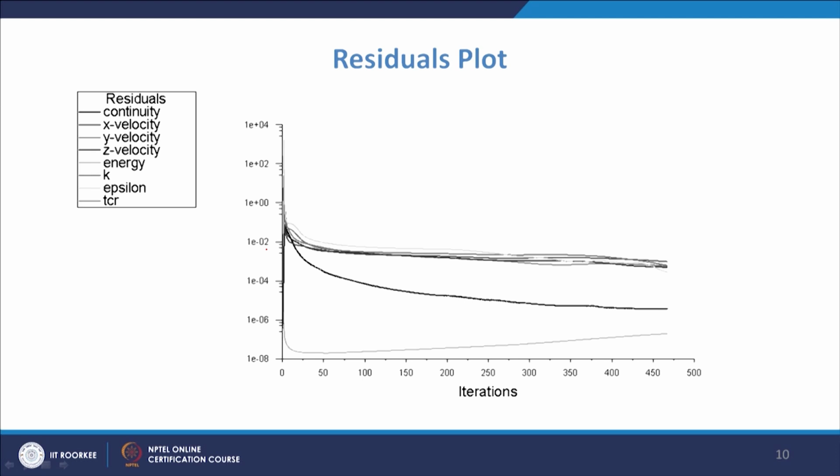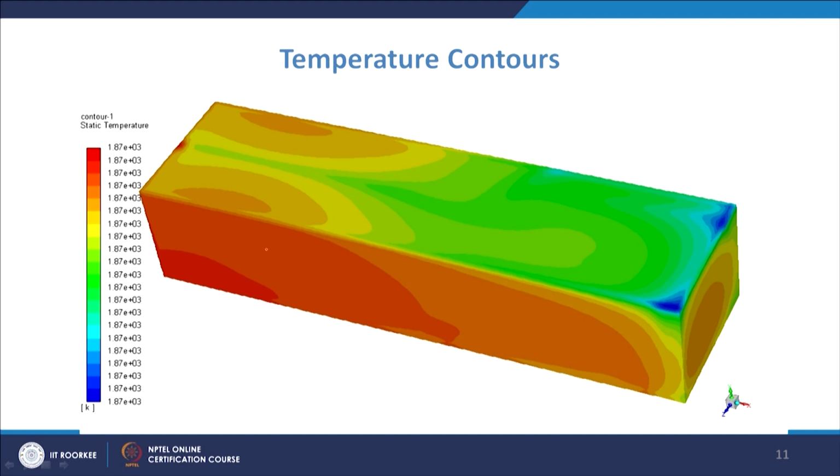Under relaxation parameters, that will basically be changing how much, in what way you are going to incorporate those changes for getting a proper meaningful result from the earlier iteration value to the next iteration. So, that way these relaxation parameters are being used. This ensures that the equation is properly solved and converged. Then, once you ensure that you are getting a converged solution, you go to get